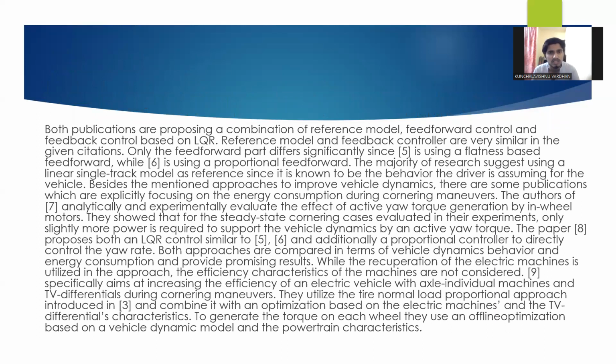Both publications are proposing a combination of reference model, feed-forward control, and feedback control based on LQR. The reference model and feedback controller are very similar in the given citations; only the feed-forward part differs significantly, since one is using a flatness-based feed-forward while the other is using a proportional feed-forward. The majority of research suggests using a linear single-track model as reference, since it is known to be the behavior the driver is assuming for the vehicle.